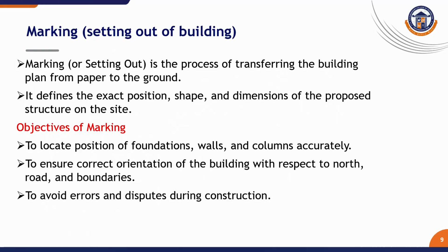Then the second important thing is marking. Marking is the process of transferring the building plan from paper to the ground. So the plan is transferred onto the ground. It defines the exact position, shape and dimensions of the proposed structure on the site.